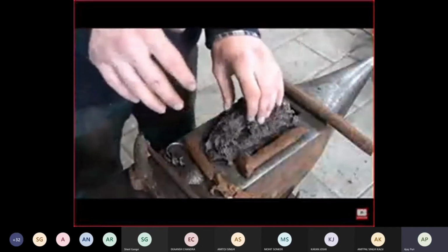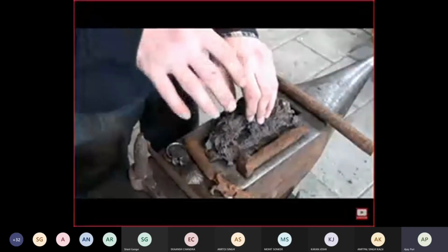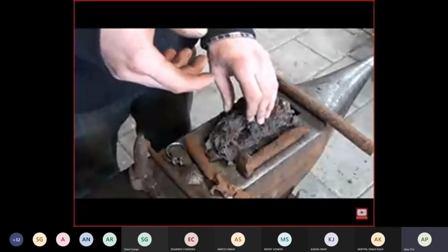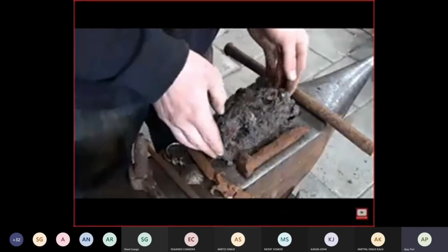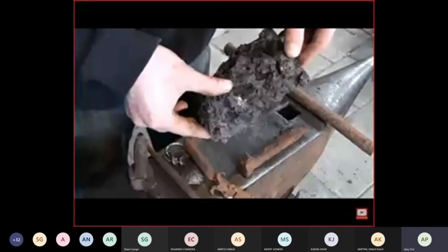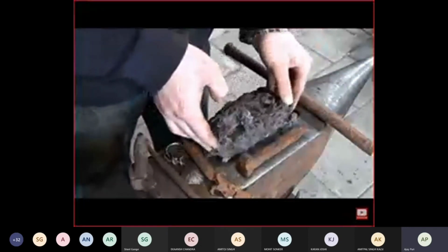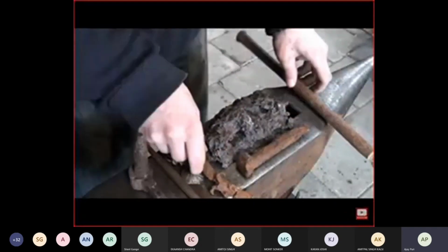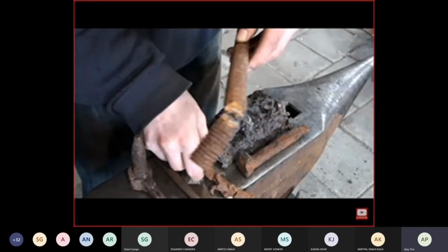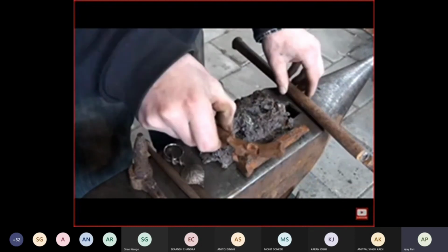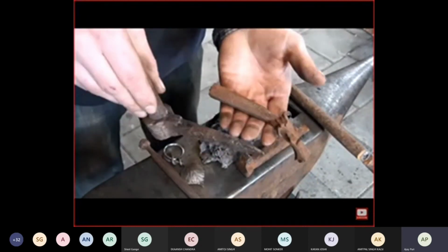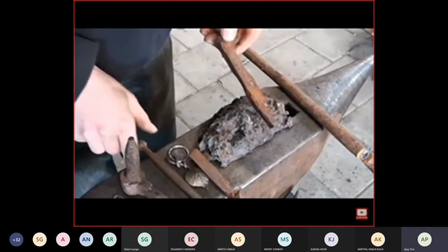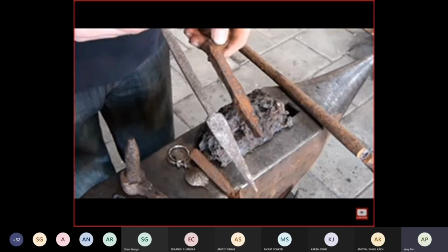And then at a certain stage, as the carbon goes out of the cast iron, the more carbon is released, the higher the melting point will be. And at a certain stage, it will also turn into a sponge-like material like this, and then they can take that out of the puddling furnace and turn that into new bars. And that is what this stuff is. This is not charcoal iron. This is charcoal iron. But all this stuff that I've got here is very likely, and I'm quite sure, all puddle iron. And all these methods to produce this iron are very expensive.